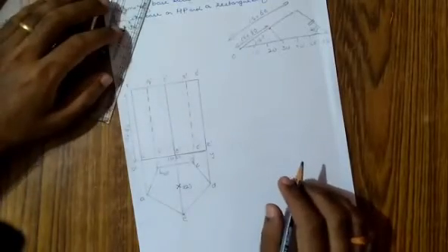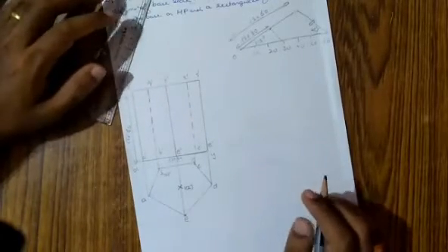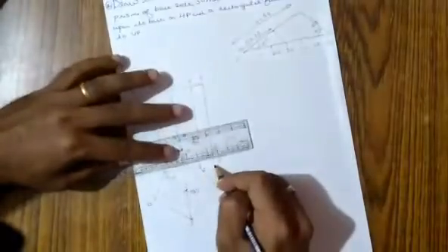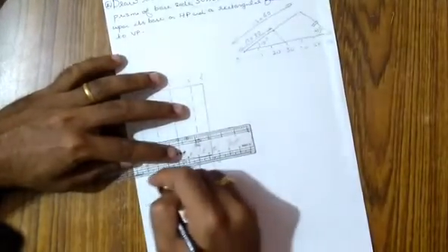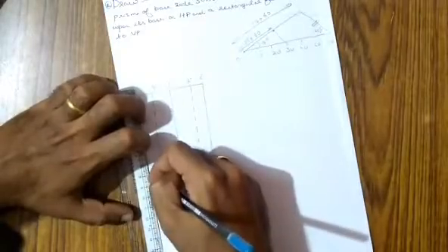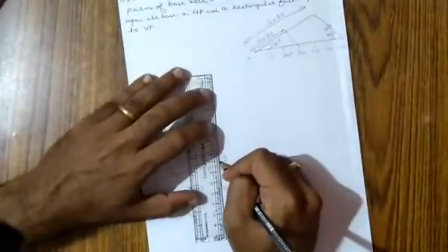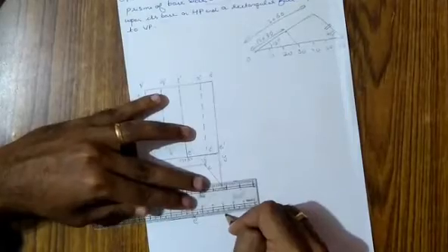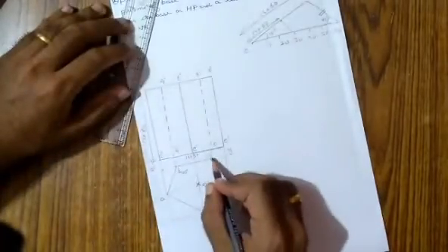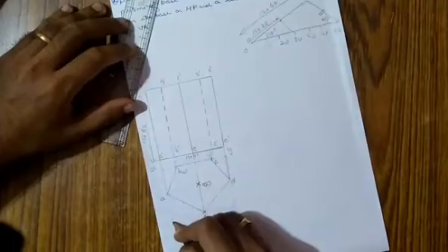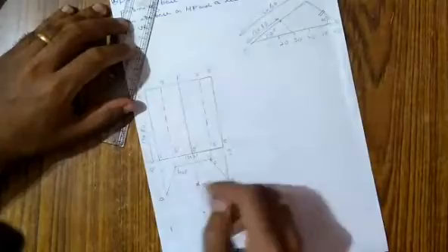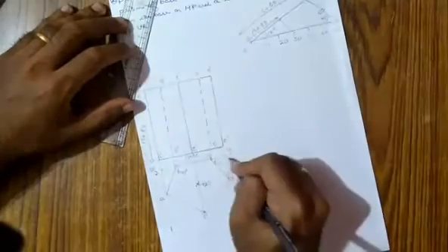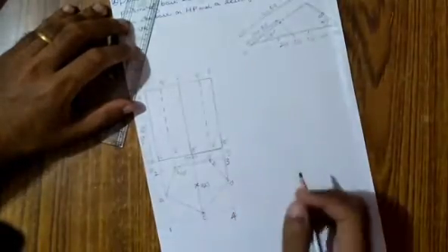Now let's draw the isometric projection. So for that, we need a reference or a salient point. So what we do first is we will enclose this solid in an imaginary box. So this pentagon is contained in an imaginary box. So this is the rectangular box inside which this pentagon is contained. So let's name the corners of this imaginary box as 1, 2, 3, and 4. Let us take the cyclic order 1, 2, 3, and 4.